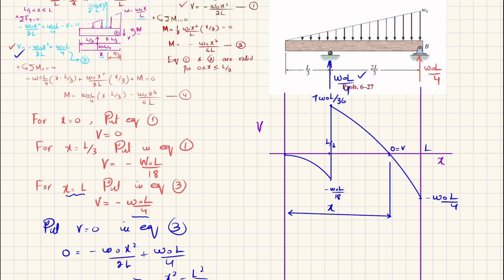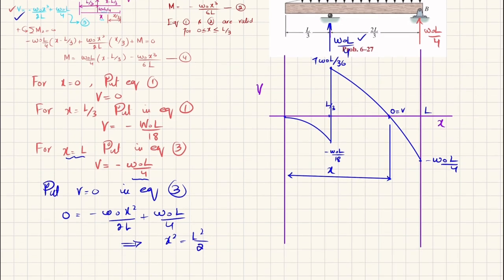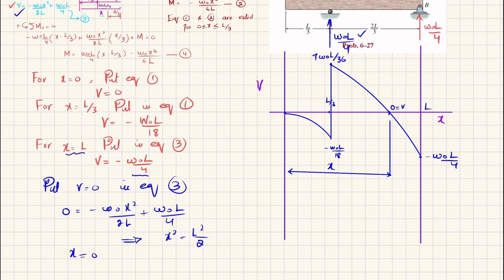And we will get X is equal to 0.707 times L. Okay. Now we'll move toward drawing the bending moment diagram. For that, I will draw a horizontal line from the end of the beam to show X in length, and we'll extend these sides. Okay. On the y-axis, we will be having moment.